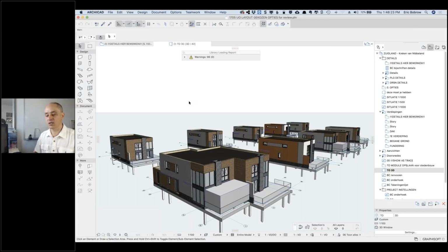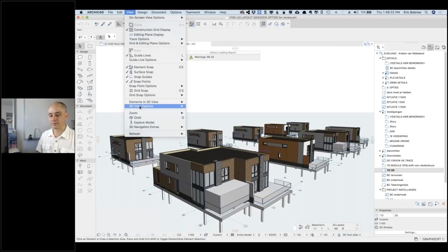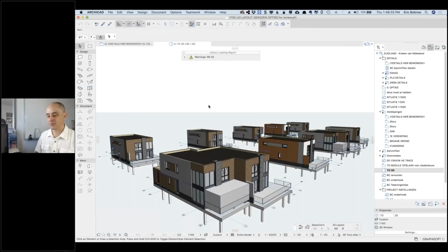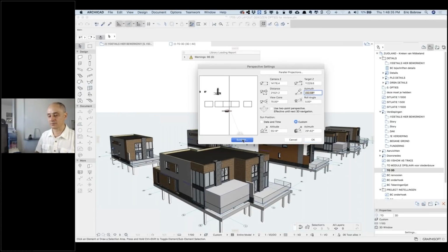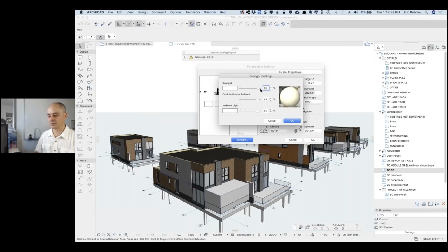And now let's just say that this is a view that's actually quite helpful, because I always struggle with that, and it's probably in the template because it's always too dark. What I always do is go to this setting and change the sun to face the facade I'm in, and that's tedious. So I should change that. So you can do that.